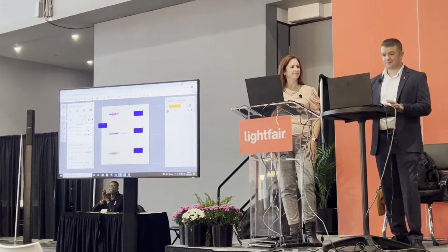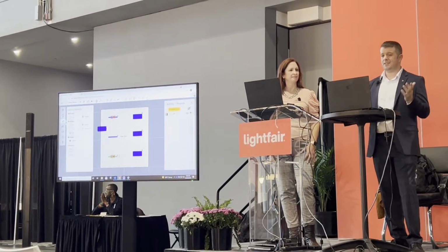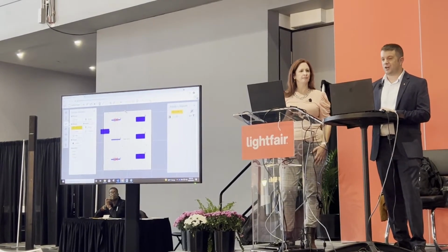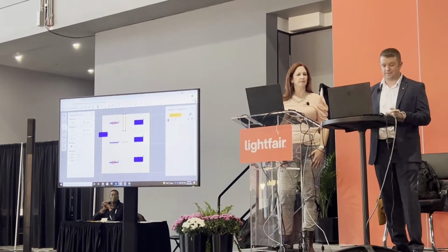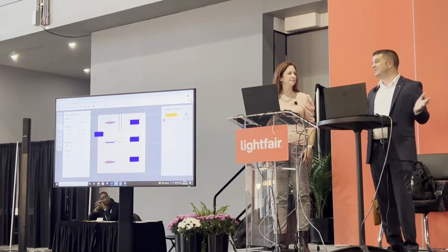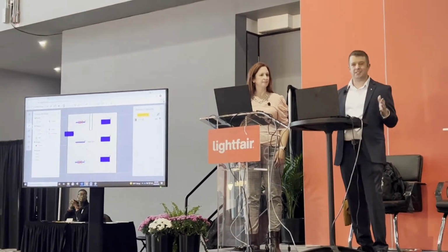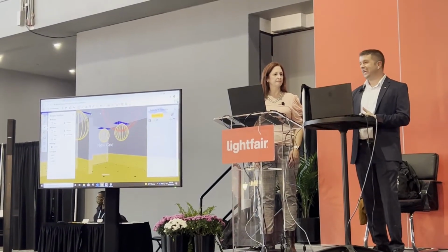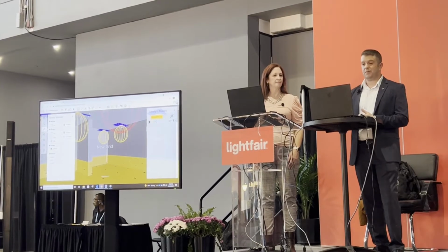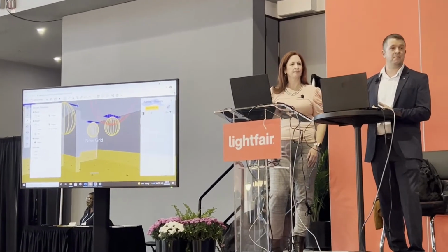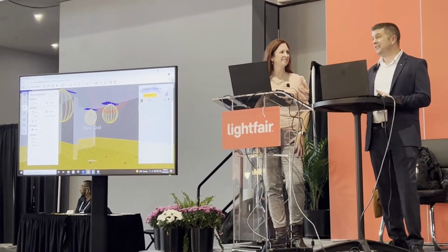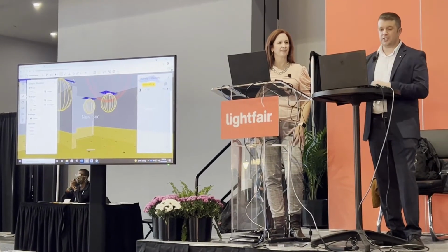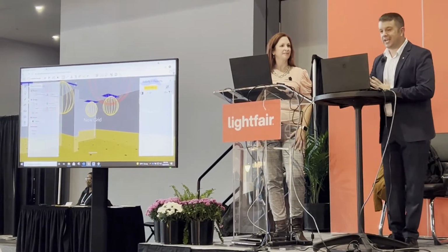It's that easy. I'm also going to add a wall in here because, you know, how many rooms are just normal geometry? So I'm going to pick a box, just draw it from here to here, put a wall in like that. Now you might be asking, what does this look like in 3D, right? This whole time we've been in 2D. I can click anywhere in this room, say view location in 3D. Here I am. I can see the entire room. I can move around, turn. I've got all my photometric webs here to make sure that none of my fixtures are oriented the wrong way. And I do have some calc grids here, 30 inches above the floor, but you know what? Maybe I want more calc points than that.